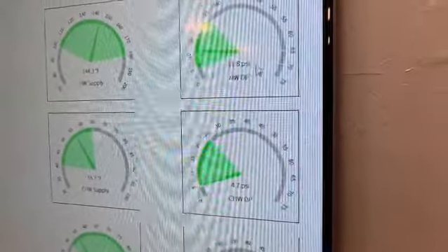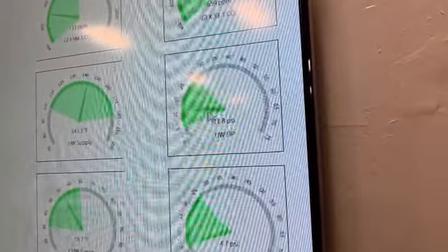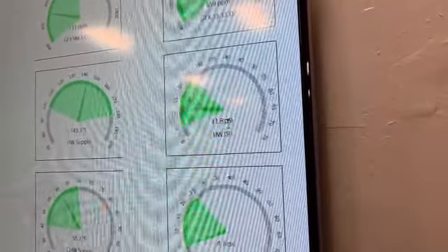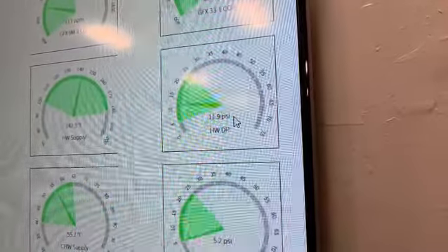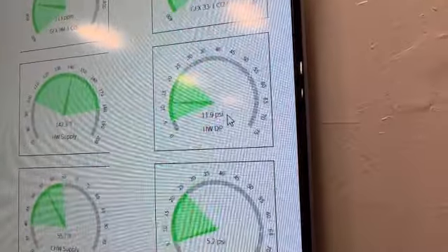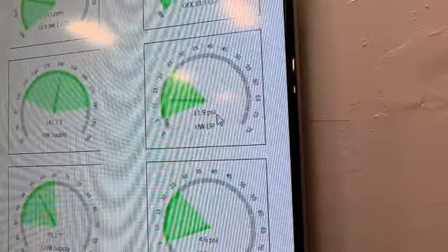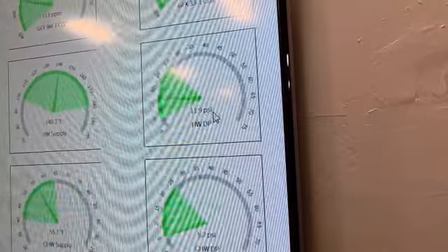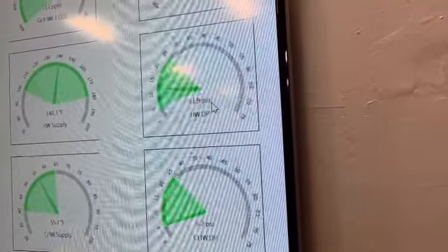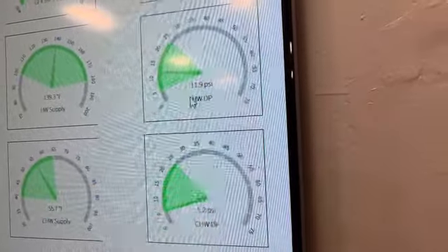So this is how you control the VFD speed, right? This is all mechanical. The engineer will tell you, we want to keep whatever. In this case, it seems like it's 12 psi, I would say, or maybe 15. I don't know, but they're gonna give you a setting. The engineer that designed the system will give the control company a set point. He's gonna say, I want 12 psi across my lines, right? So that's what it is.